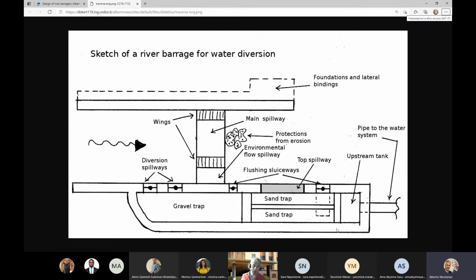And you should say, because I want to avoid that air gets into the pipe, because air in a pipe that is under pressure causes potential damage. And then I could ask you, what is the minimum submergence that we have to give? And then you should say, okay, it's at least 1.5 times the kinetic energy of the pipe flow.